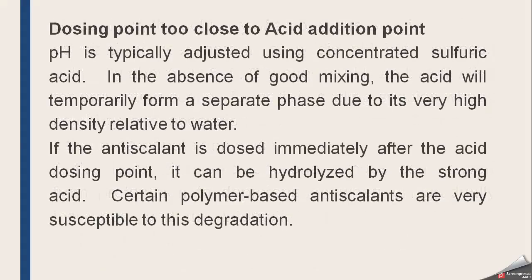Now the other important point is a dosing point too close to acid addition, that is, the dosing point of the antiscalant is very close to the acid addition point, because we are adding acid to control the pH and adding antiscalant to control the scaling. pH is typically adjusted by the addition of sulfuric acid.